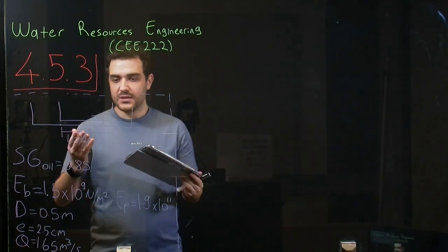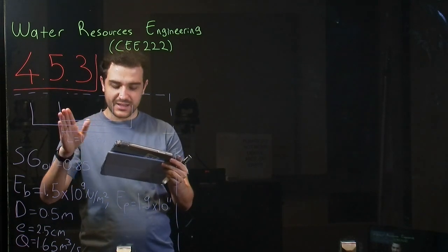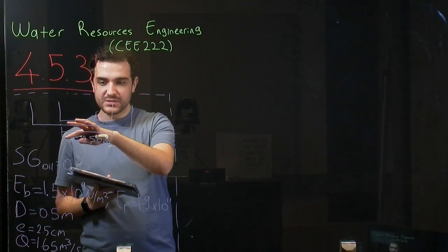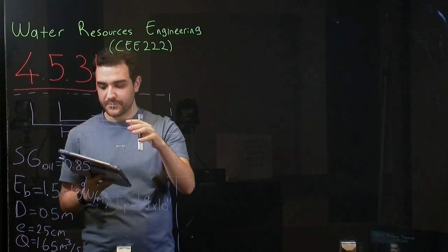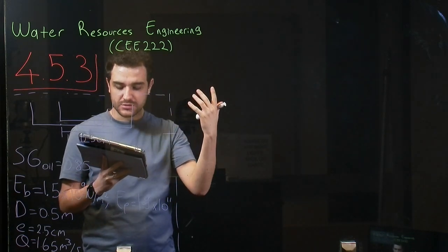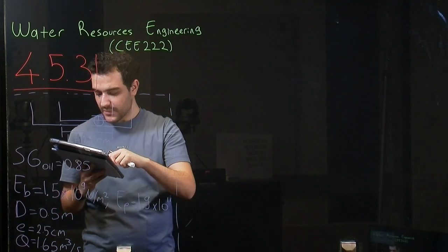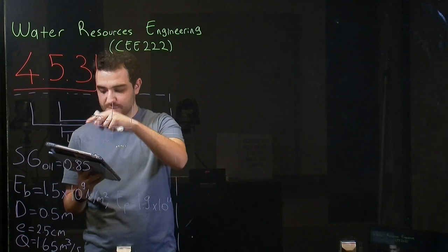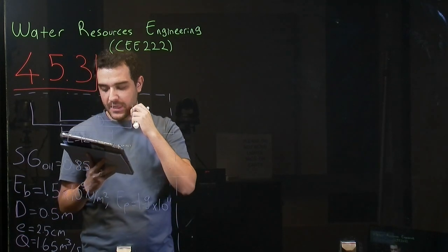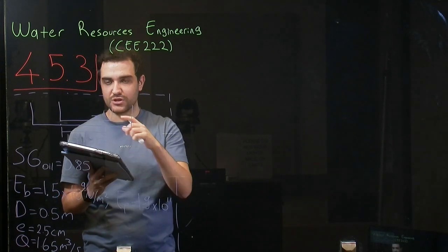So if we close this valve, a sudden change of flow rate in a large pipeline like this one may affect the large mass of water within this pipe, and valve closure or pump shutoff can cause this sudden change. Changing the speed this much could cause a pressure rise, as mentioned in the question, and the pressure could be several times greater than the normal static pressure.